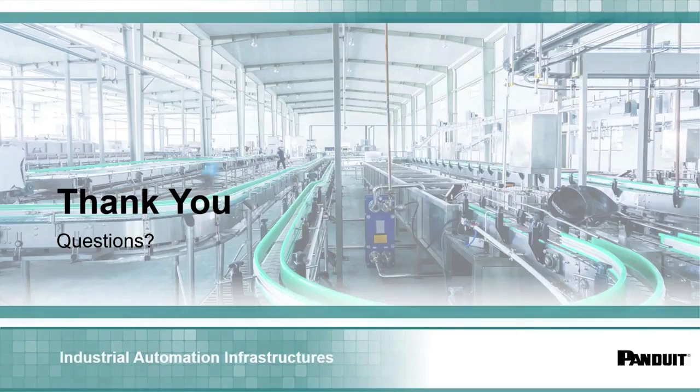Yes, home runs are fine. As soon as you move into a larger installation, I think you'll find the benefits of a distributed architecture will outweigh the costs. And then also it gives you so much more flexibility. So I would really only ever recommend the home run methodology if you've got guarantees that you're really not going to be doing any expansion.